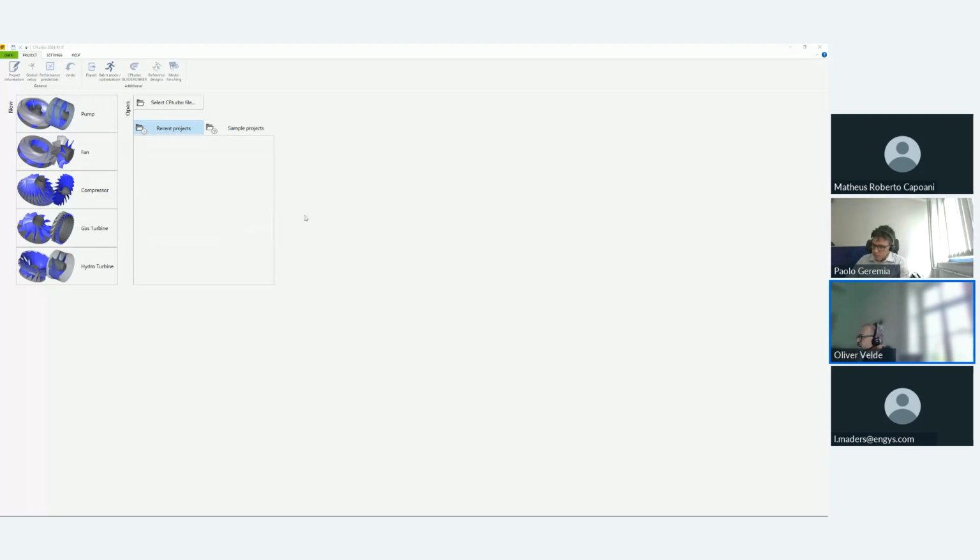In every design step, we give information that you can use for getting feedback on what you have done so far, and also make use of in order to get some empirical results based on this. Here, for instance, the specific speed is calculated once I change the focus, or we get the location of that operating point in the coordinate diagram, and from that you can immediately say what is roughly a good diameter for your, at least single stage, pump. And that's the case for every design step.